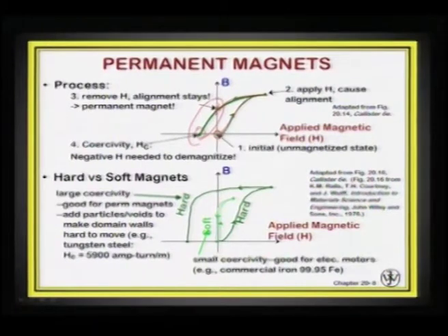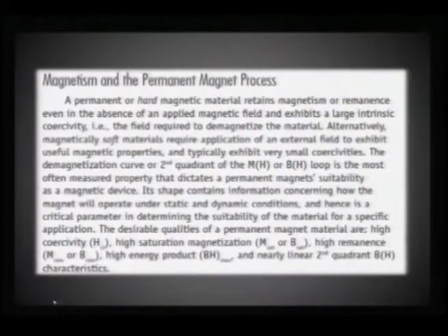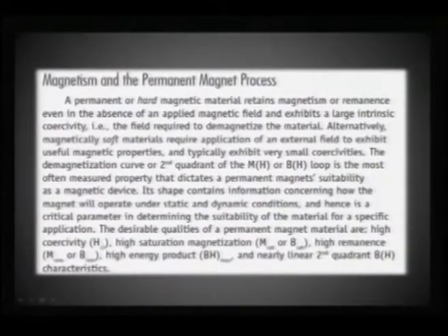And as you would see here, for a permanent magnetic material, when you try to reverse the field in the second quadrant, whatever is happening here will tell you the nature or the strength of your magnetic material. So, compared to a soft ferrite, which is here, a hard ferrite or a hard magnet will actually have a very high hysteresis and large coercivity, and therefore, this can be used as a permanent magnet. So, what is the parameter that we use to ascertain a permanent magnet? We can just look at it briefly.